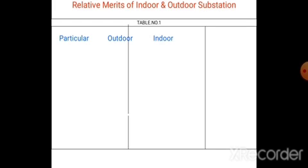The table indicates the relative merits of indoor and outdoor substations. The space required for an outdoor substation is more, but less space is required for an indoor substation. In an outdoor substation the erection time is very short because it is visible, but in an indoor substation it is much longer.